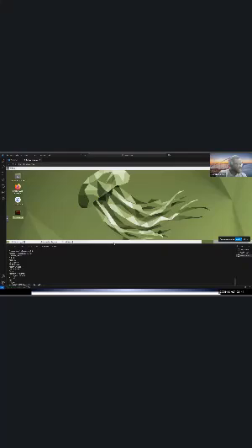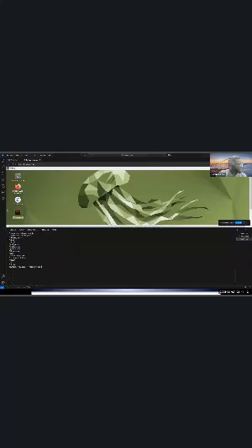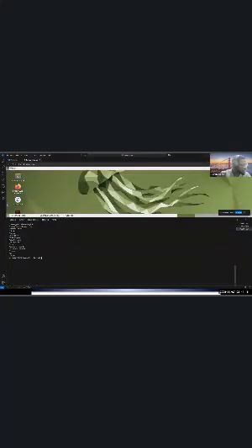You see that over here in the terminal, when I do ros2 topic list, we have cmd_vel, we have the camera topic, we have TF, like Devin told us. TF is a very important topic, that's the basic that we need. And ROS output, the robot description topic, then the odometry topic. Odometry is what we use to track the robots. Then joint state. Now we do have a scan topic, but we remapped it.